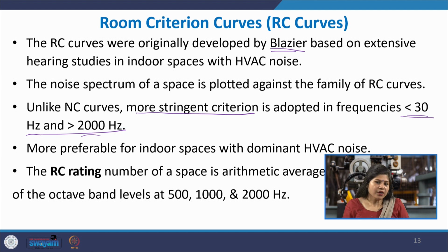So even if the ear is not very sensitive, sound at low frequencies can lead to vibration of the structural elements, making the room susceptible to structural damage. Having a very high level at lower frequencies is not desirable, because it will induce vibration and cause wear and tear of the elements in the room, and hence these stringent criteria.